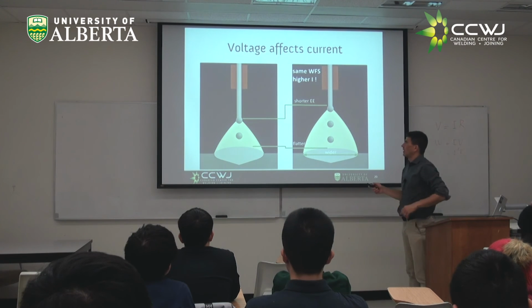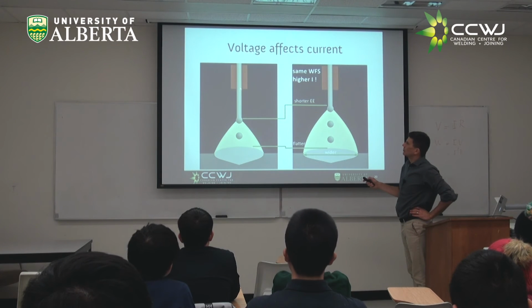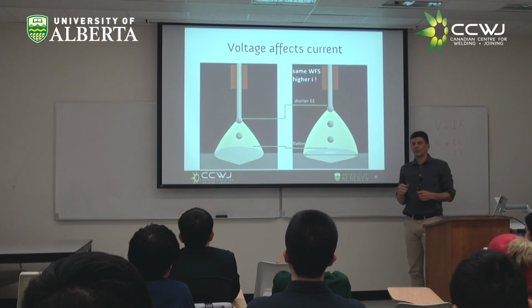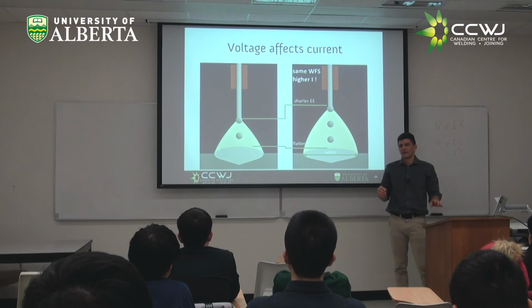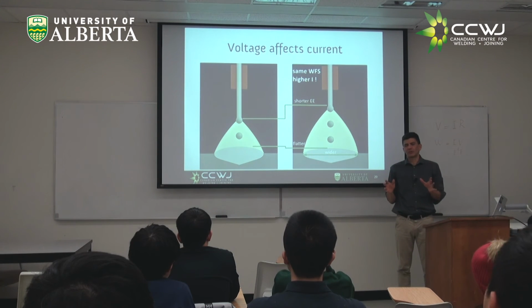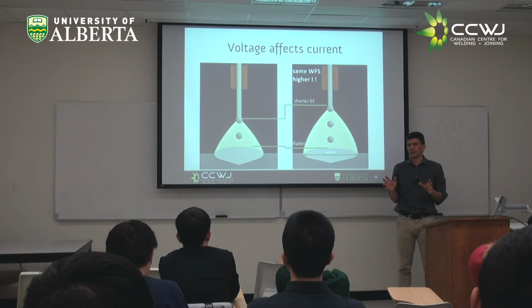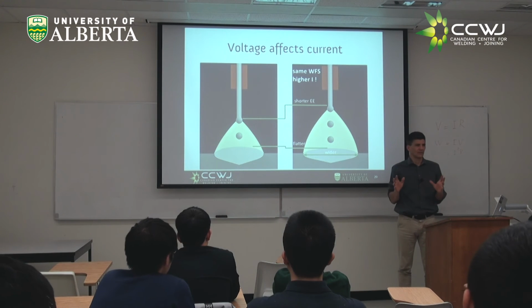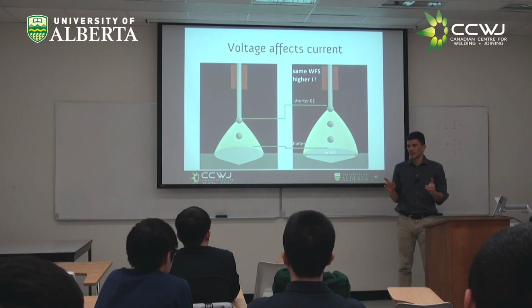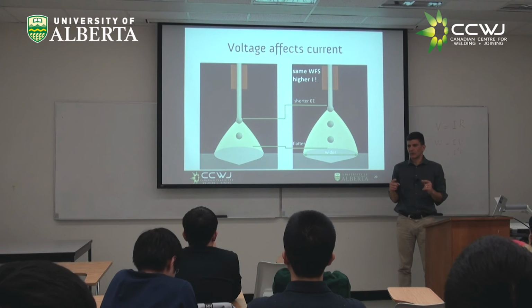So look at this. How does MIG run, on constant current or constant voltage? MIG. Constant voltage, right? And what do I change to affect the current in MIG?